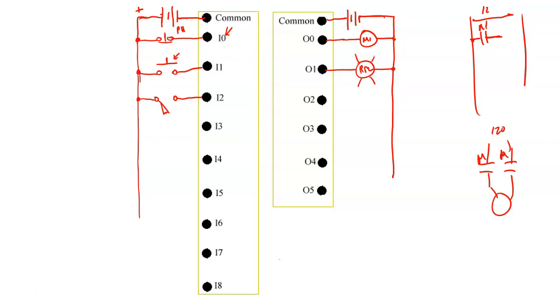Now, what you do over here, with no series circuits, they're all one load, normally one input. If we put multiple inputs, then we have wacky stuff. So even if we had two inputs in series in our relay diagram, each one of them would be assigned its own input. The inputs are not in parallel because you have an electronic circuit, and each one of them is individual. To be in parallel, this side and this side would have to be connected together. These are not in parallel. We put them in parallel inside our diagram.